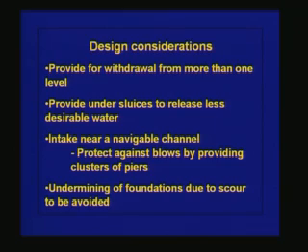If the sediment gets scoured during the high flood flows, then the river bed level itself is going to go down. If the river bed level goes below the foundation level of the intake structure, then the intake structure can get washed away very easily. So undermining of foundations due to scour should be avoided.